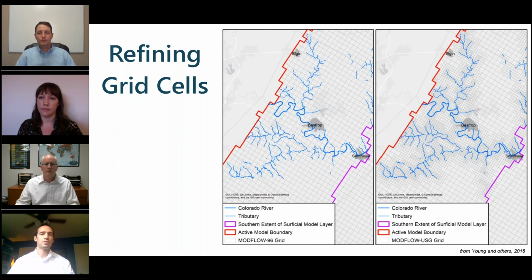So with the newest, most current code being MODFLOW 6, you have these options that you really didn't have before. And again, they're there to add resolution in areas of interest, versus having to do a telescoping model within a model, or using local grid refinement. So this is just some of the flexibilities offered with the newest, most current code.